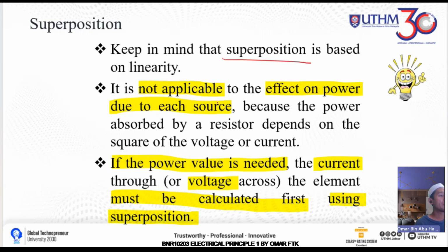So it's not applicable to the effect on power. If you want to calculate power, then not for the superposition concept. If the power value is needed, then the current through or voltage across the element must be calculated first using superposition. That means you calculate the element value and then return the circuit back to the original state, and after that you can calculate the value for the power.